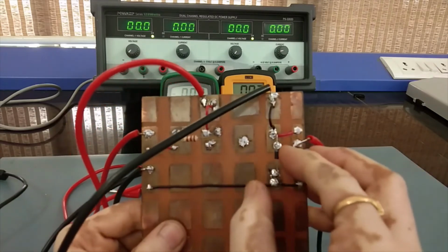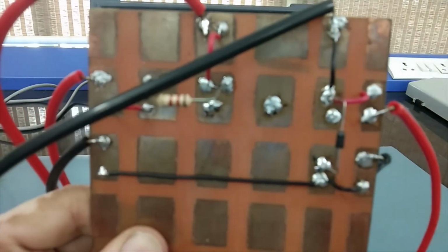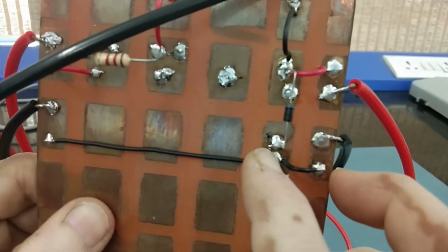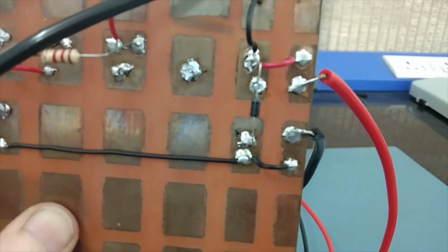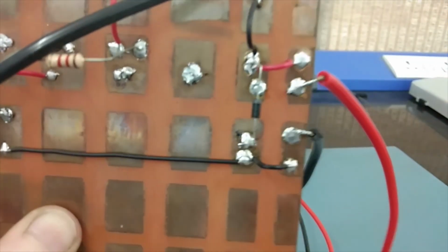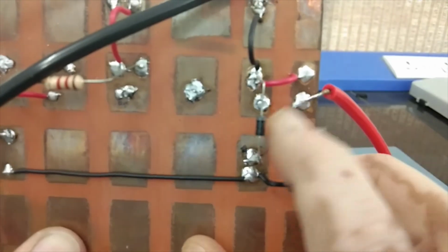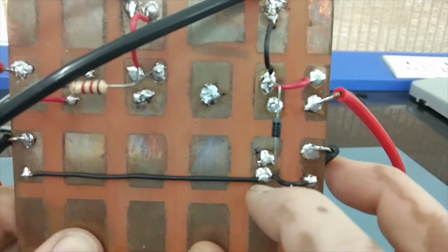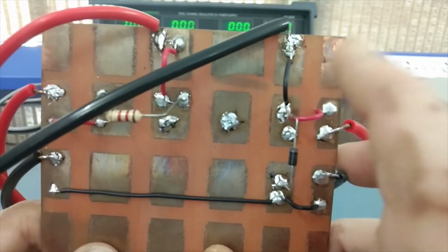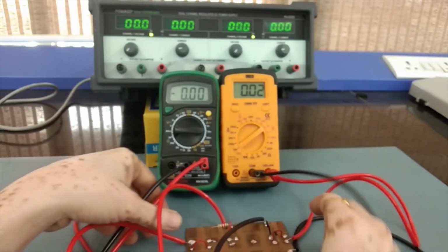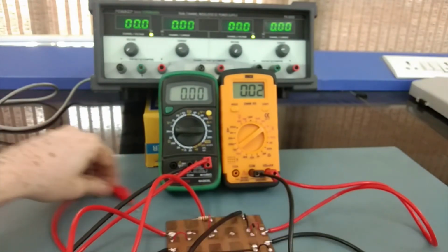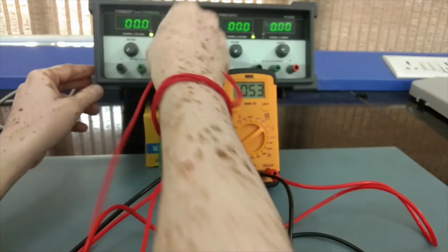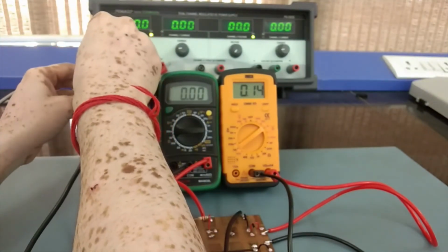Now you can easily see that the terminal of the diode has been simply changed. You can see the anode here that is connected to the common terminal of the circuit, and this cathode terminal is now connected to the negative terminal of the ammeter. So now we can say that the diode is reverse biased. Alright, we have made absolutely no further changes in the circuit. They can be all alike, and now we can connect the diode to the power supply.